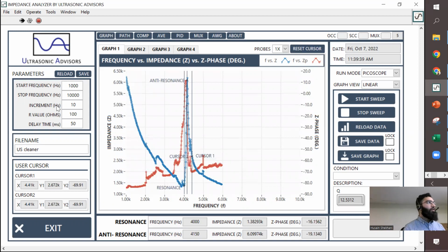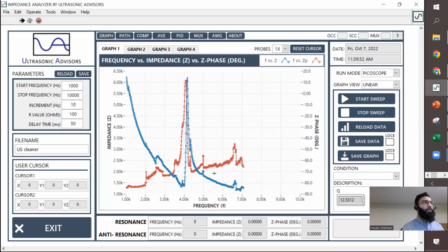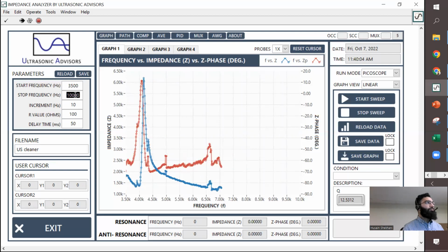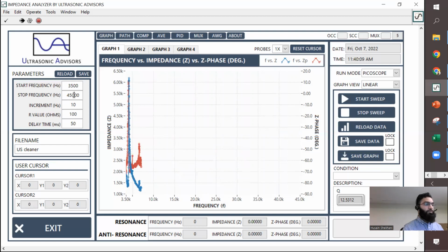One way is to increase your delay time. We know that the resonant frequency is about 4 kilohertz, or you can hold it. I'm going to be holding it up in the air pretty soon. So let's work on that buzzer and how we can get it to measure better. I'm going to zoom in around the frequency of interest so I can do measurement there. Okay. Oops, that's too much.